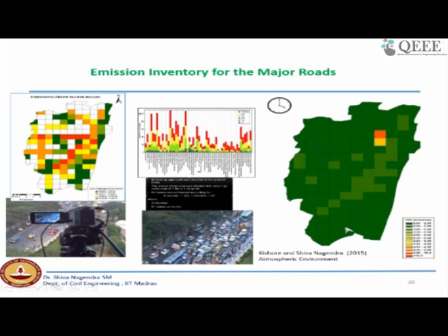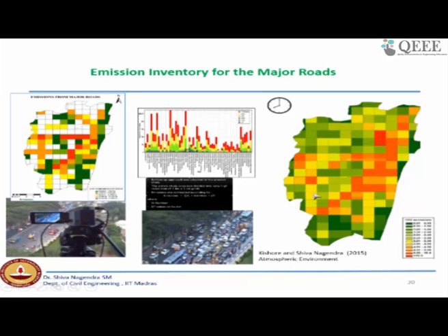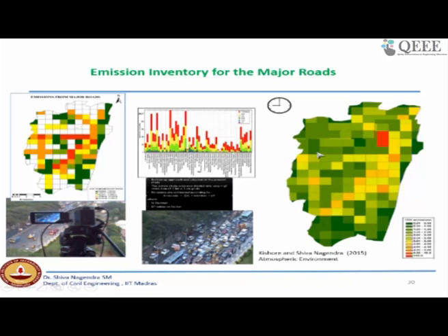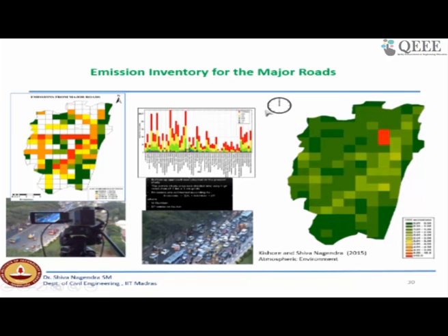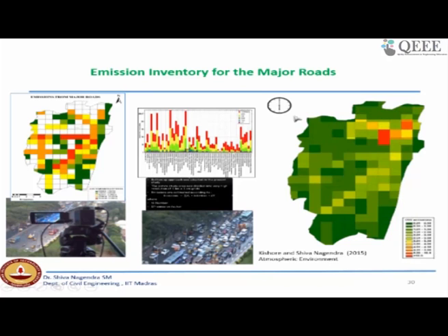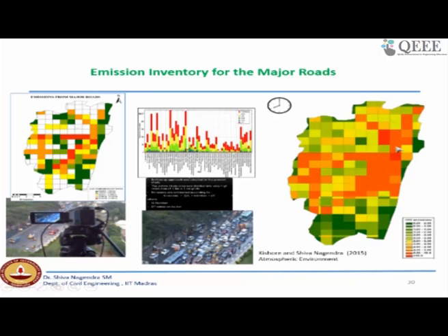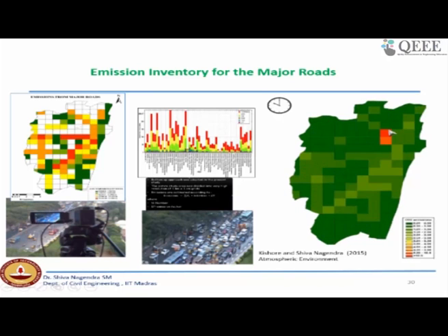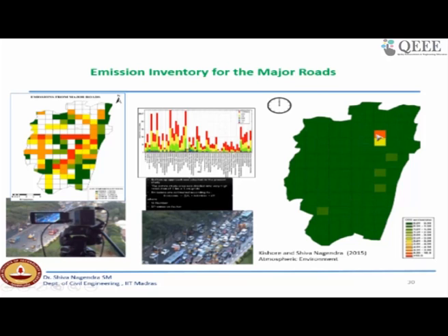So we have made a real-time estimation to indicate how pollutants change with respect to time. Now if you look at this and the time scale, at these two spots the air quality will be significantly higher irrespective of time. It indicates the location of two power plants, with stack emissions at this particular location.